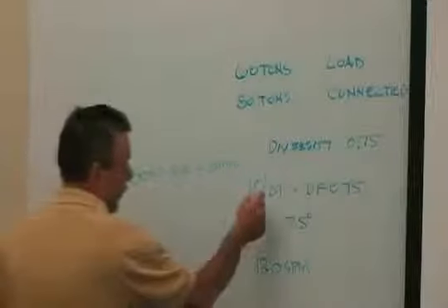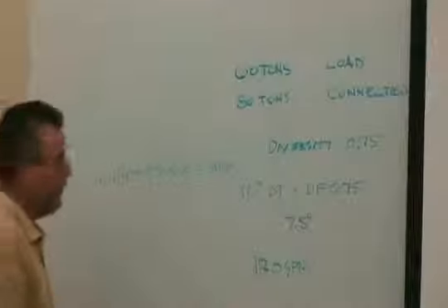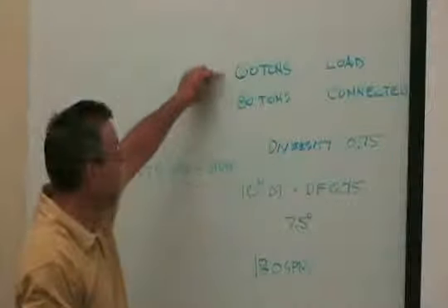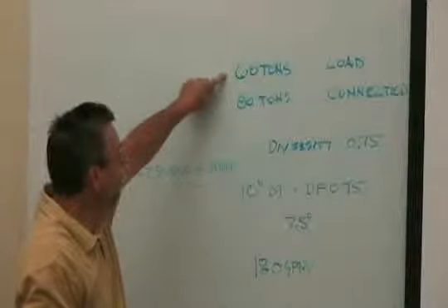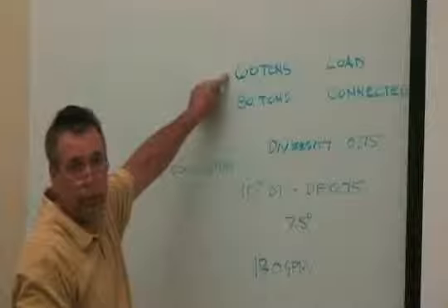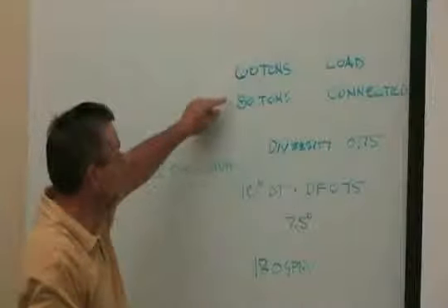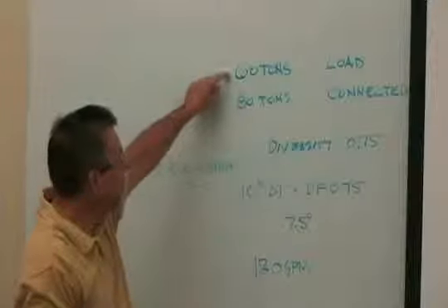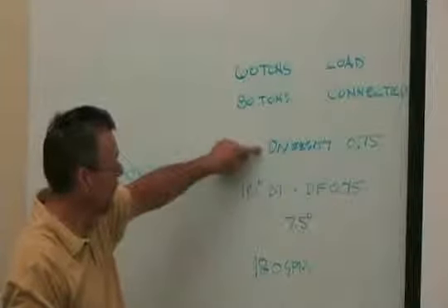So I don't have to just use a 10 degree because I've actually got diversity in my system. My load is 60 tons, and with a heat pump system, I'm not just going to size that fluid cooler on 60 tons. So I take my connected load, divided by my actual building load, come up with a diversity.